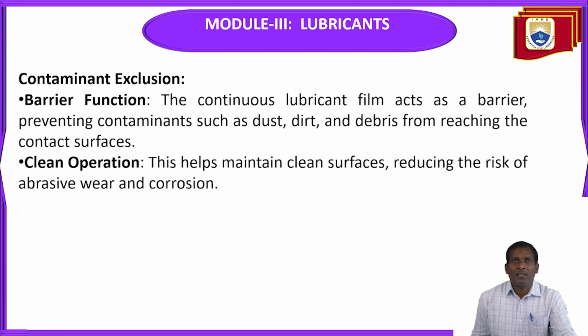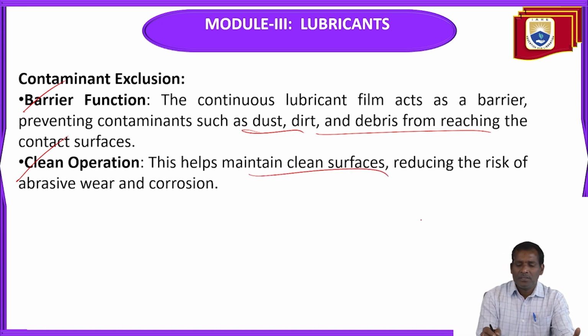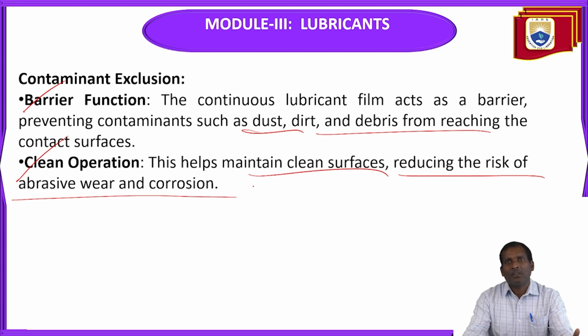So contaminant exclusion: barrier function, clean operation. The continuous lubricant film acts as a barrier, preventing contaminants such as dust, dirt, and debris from reaching the contact surfaces. Clean operation means this helps maintain clean surfaces, reducing the risk of abrasive wear and corrosion.